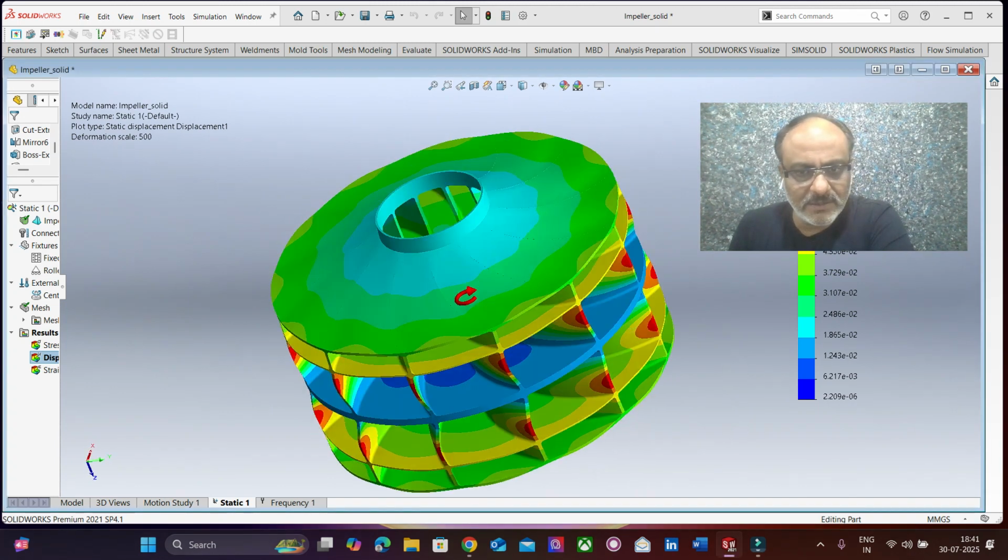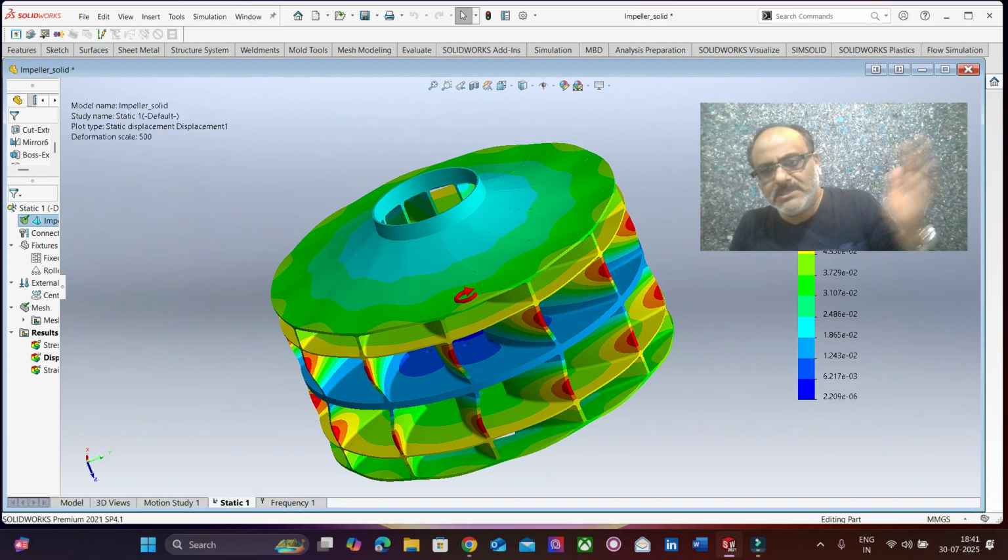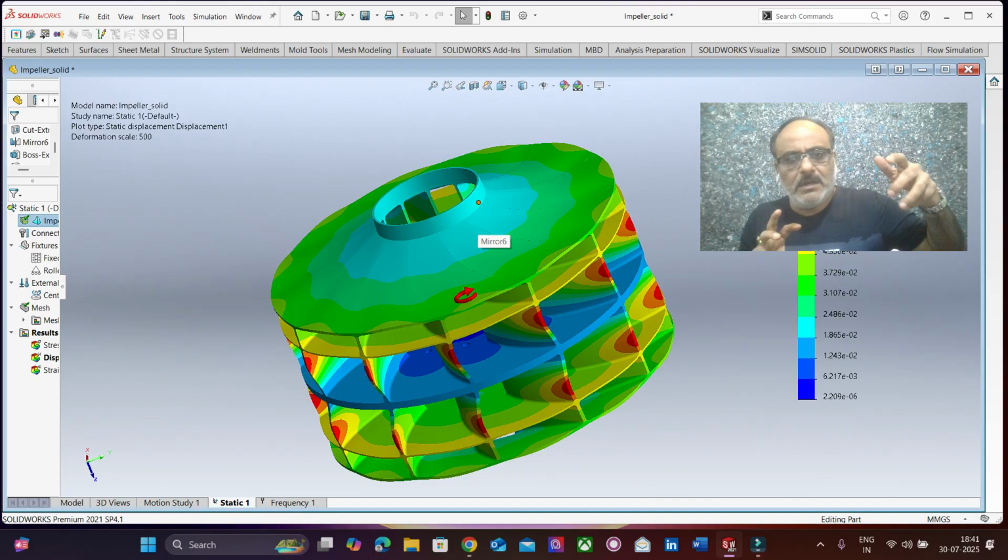We have designed the structure, and I told you there is a specific reason that we have a top crown and a bottom crown. It's basically for distributing the stress completely. Whatever stress accumulates on the system can be distributed over the crown. Moreover, the crown is a member that will be able to stiffen against the torsional loads, because here there is going to be an enormous amount of torsion induced.